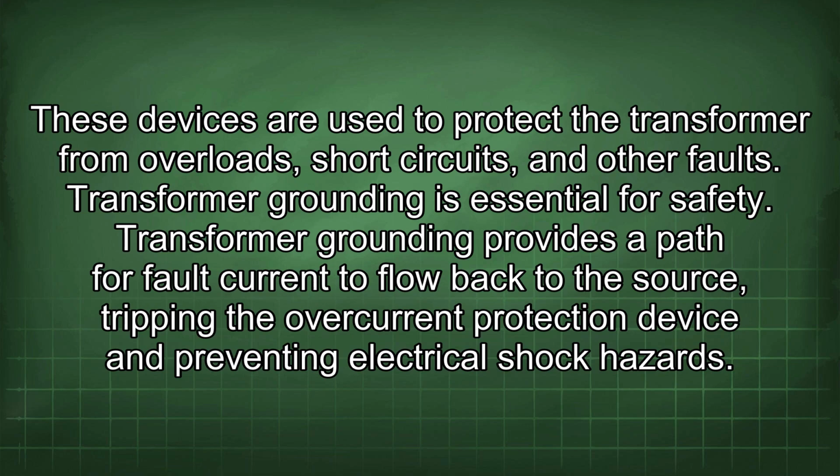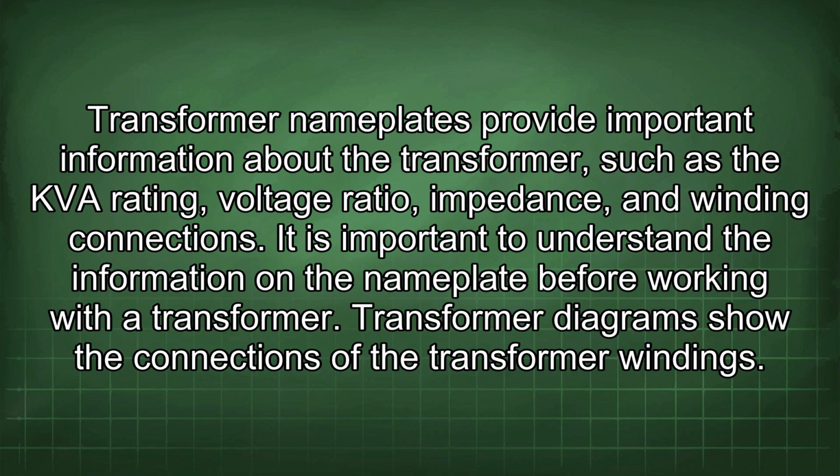Transformer grounding is essential for safety. Transformer grounding provides a path for fault current to flow back to the source, tripping the overcurrent protection device and preventing electrical shock hazards. Transformer nameplates provide important information about the transformer, such as the kVA rating, voltage ratio, impedance,